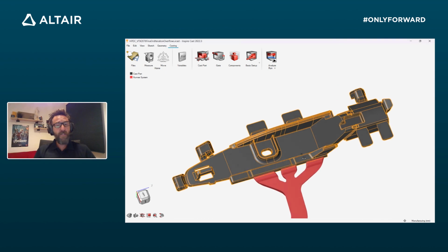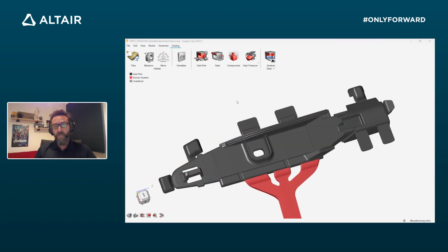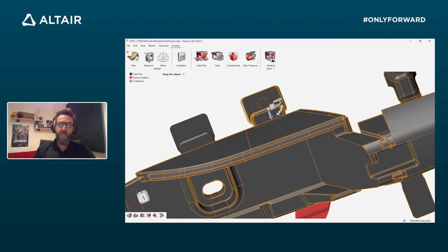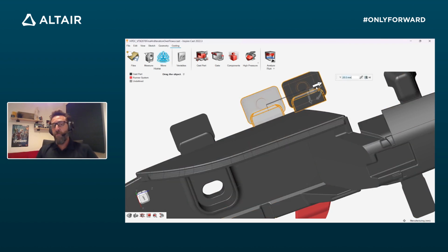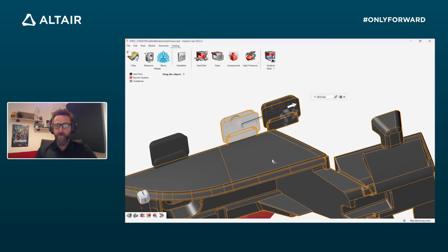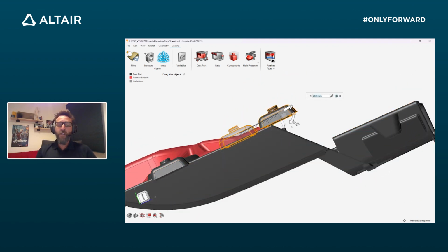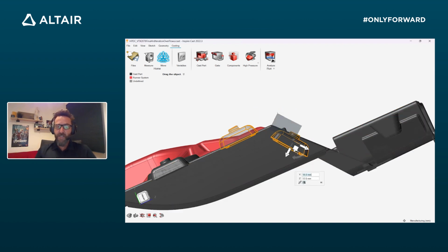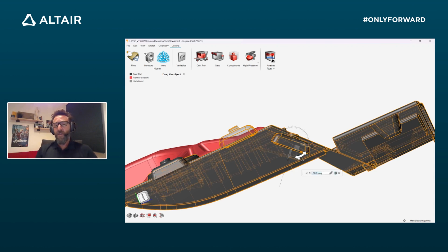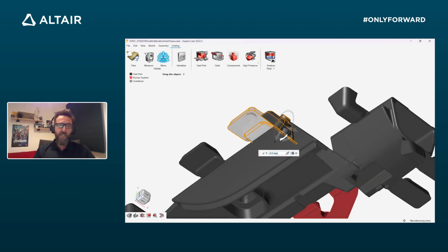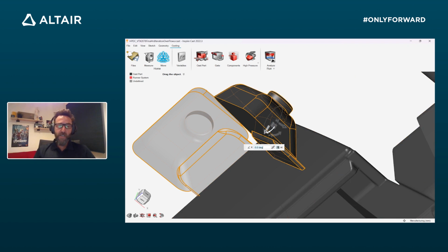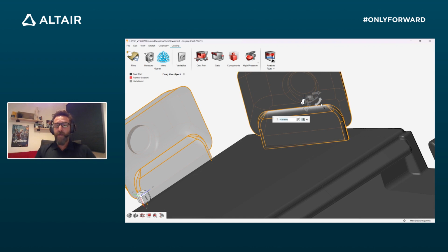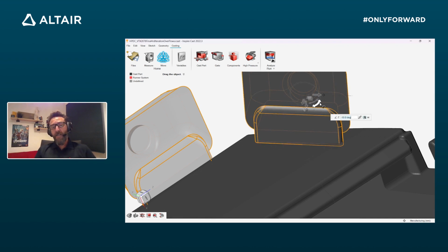What can we do? Basically, we must move the overflow, and this is extremely easy and simple to do in InspireCast. You grab the overflow, use our move tools, and reposition the overflow close to the required area. You can see how easy it is to modify the overflows, and all our geometry is parametric. Every change I am doing right now, I can control later using parameters.